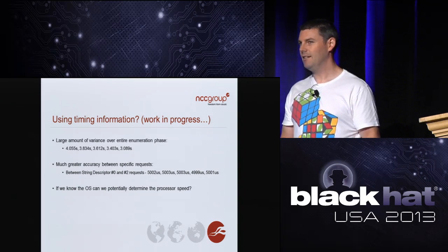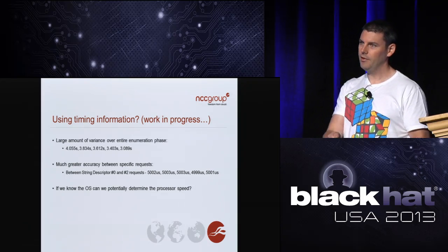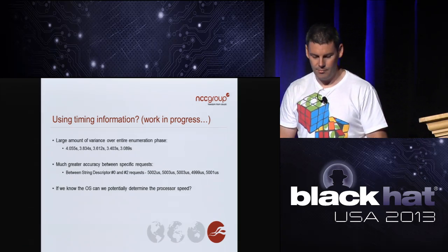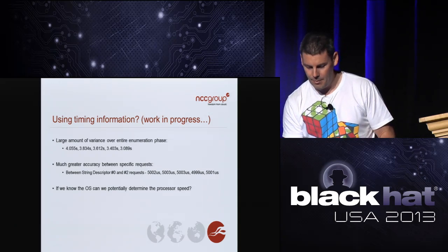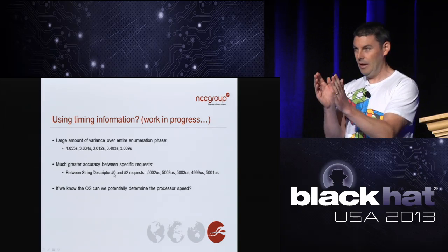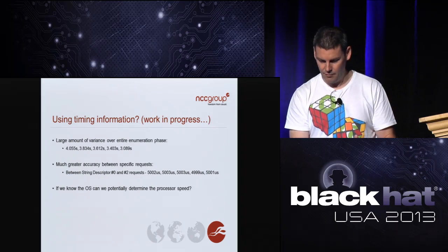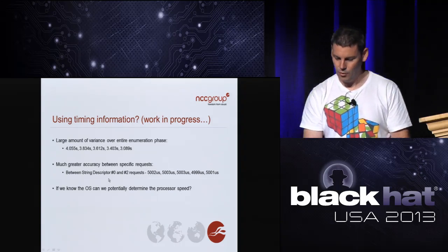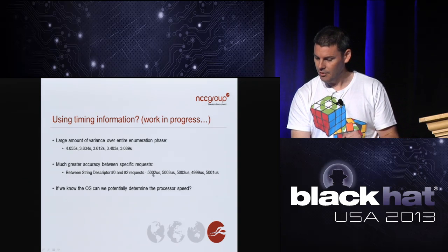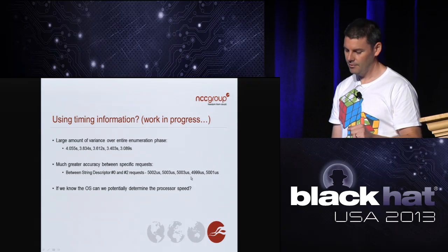It typically takes around 5 or 6 seconds to go from initial device insertion to the point where class-specific communications are occurring. But if you tie it down to the timing between specific elements within that enumeration phase, here I've looked at the difference between the timing of the request for string descriptor 0 and string descriptor 2, you're talking of a difference of 1 or 2 microseconds.